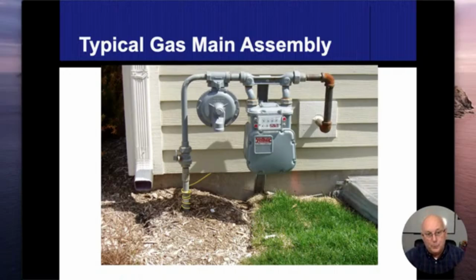So this wire wraps around that plastic gas pipe, so they could put, I think it's called a sonde, something where it creates a signal, and then they could run their finder over the top of that, and they can mark exactly where the gas line is, so that we don't dig into it.